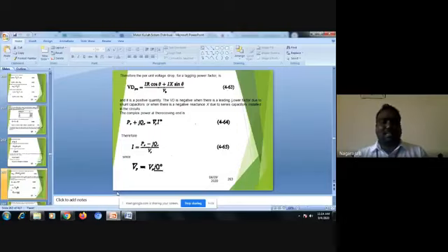So voltage drop can be negative. There are possibilities of negative values also when there is a leading power factor, due to the shunt capacitors, or where there is a negative reactance due to the series capacitors installed in the circuits. Okay, this is about the voltage drop per unit calculation.